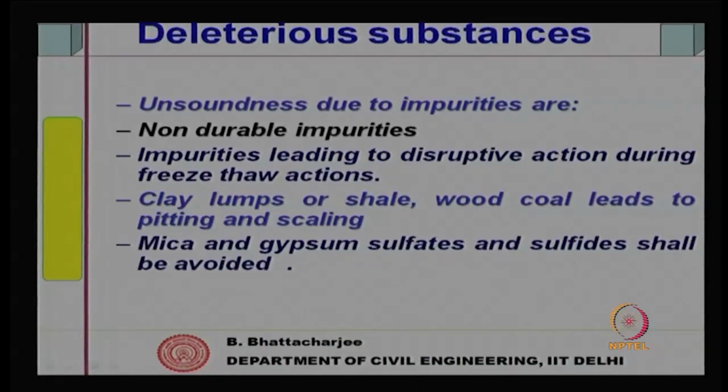Mica and gypsum, sulfates and sulfides shall be avoided. Some result in a kind of unsoundness, in the sense that there will be expansive changes, durability properties will be hampered, and disrupting action during freeze thaw actions could be there.